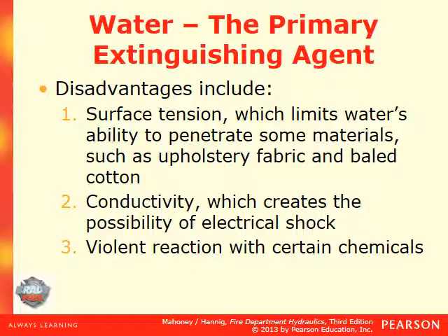For example, the engine block in the old VW Bugs is magnesium based, and when they catch on fire, you add water to it, it's going to cause an explosion type reaction, and then it takes, again, copious amounts of water to put that fire out. A lot of times with those types of materials, a powder extinguishing agent does better.